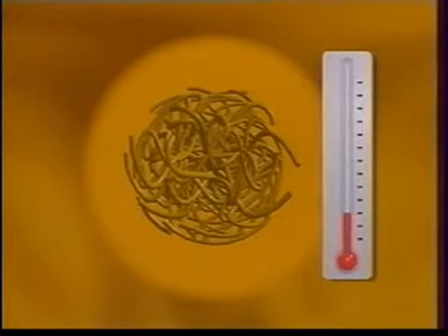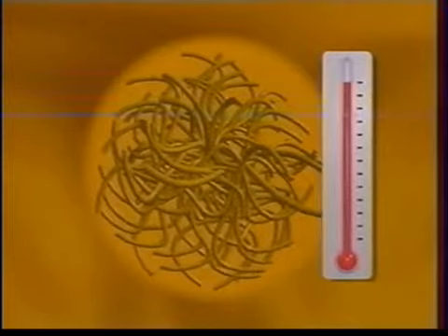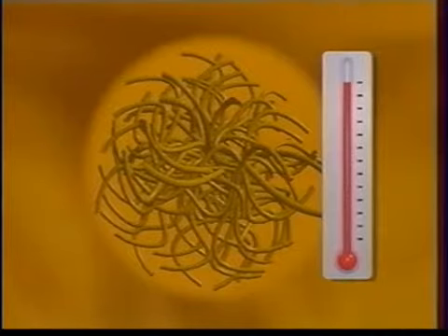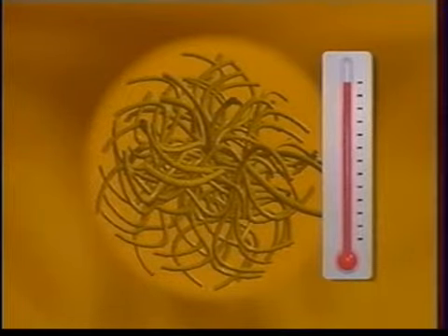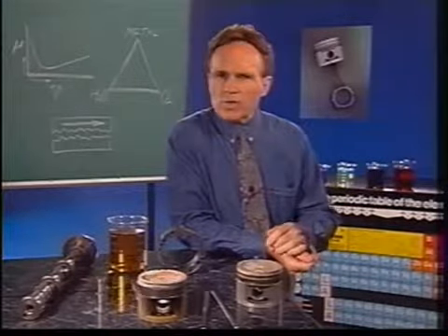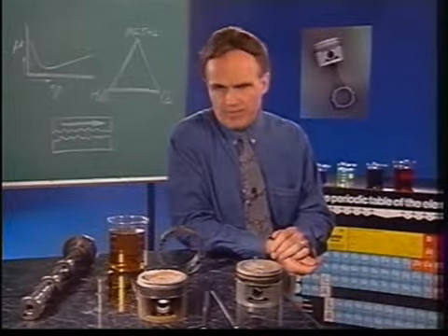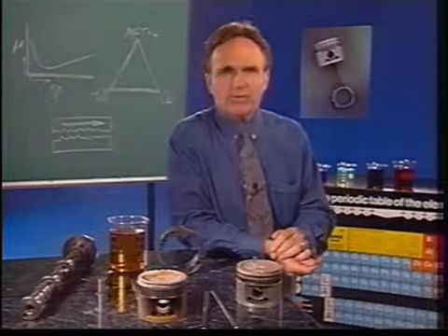At low temperatures, where high viscosity is undesirable, the polymer molecules occupy a small volume and have minimal association with the bulk oil. At high temperatures, the polymer chains expand. This increases the polymer's association with the bulk oil due to expanded surface area. The effect is to increase the viscosity. Viscosity modifiers extend the temperature range over which a lubricant can function effectively, an important feature for fluids that must